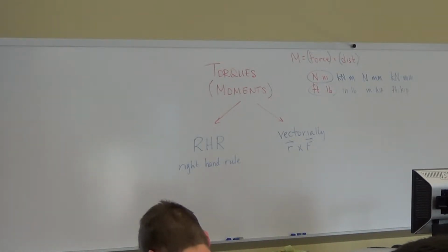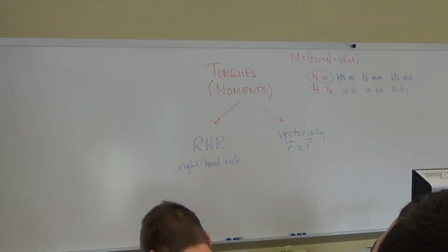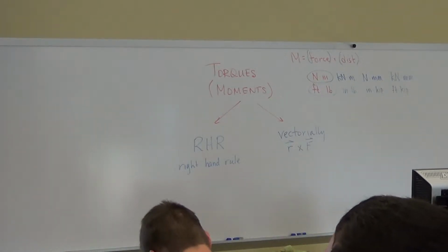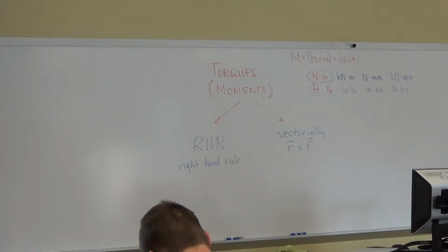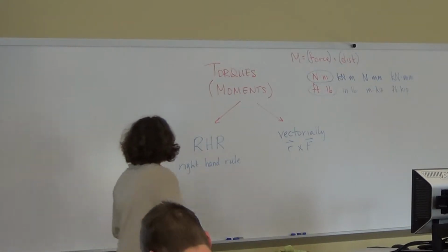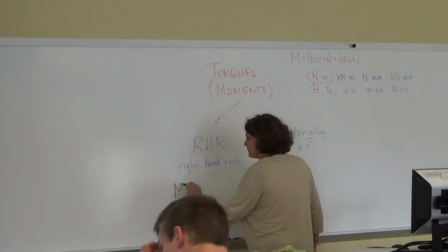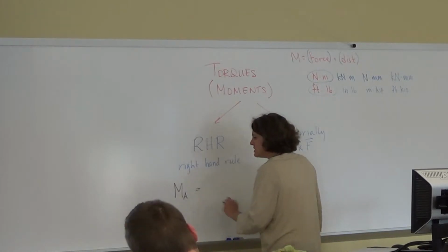Statics is the study of forces on bodies, so force is really the subject of my sentence, and the distance just tells me how much my moment can be. So for me, my fingers are the most important, and I put it in the direction of force, and my palm towards the point. So going back to right-hand rule, how do you calculate the moment? What's it equal to?